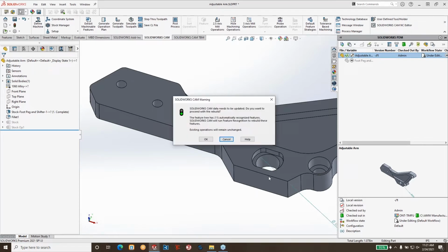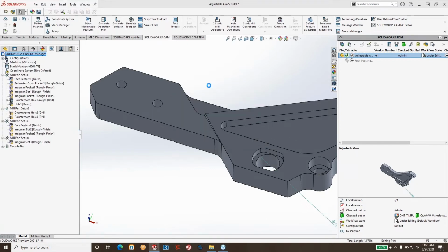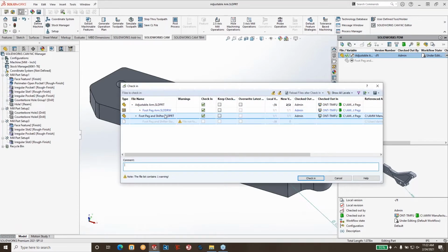That'll work. And the other bonus here is when I'm doing all this, it's updating the CAM at the same time. So if I hit OK, it is now modeling all that, and it's actually adjusting my tools to fit inside there properly. So huge benefit to being inside SolidWorks and doing all your machining inside SolidWorks. So now I'm updated, I got the right information in there, and then I can make a comment, you know, made 0.125 on fillet. Made correct. Perfect.